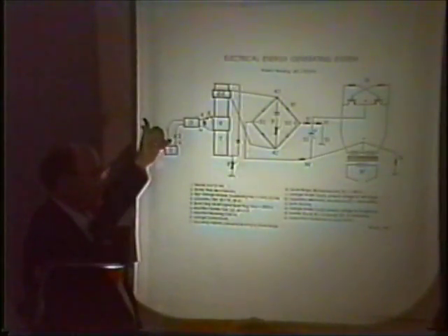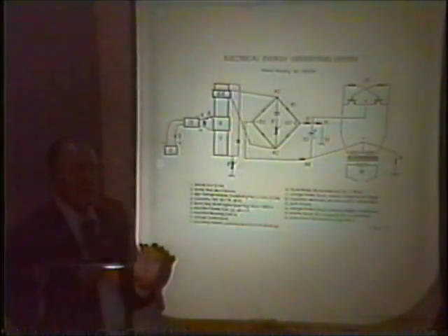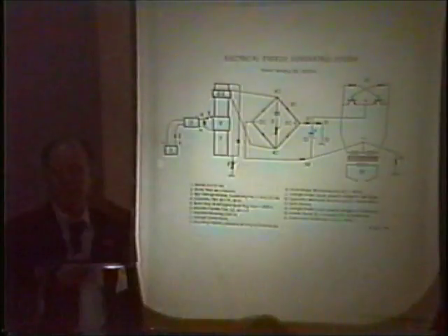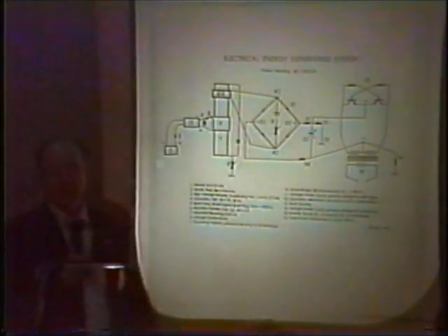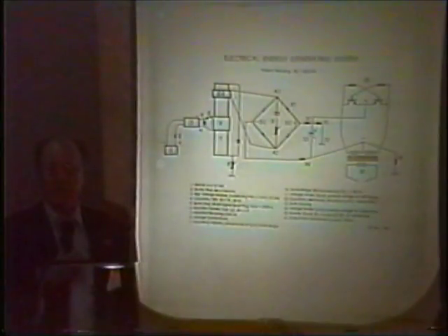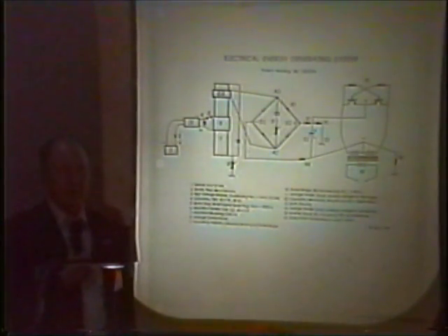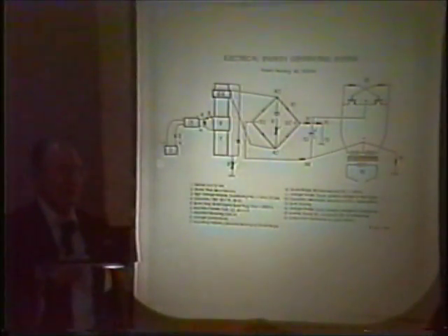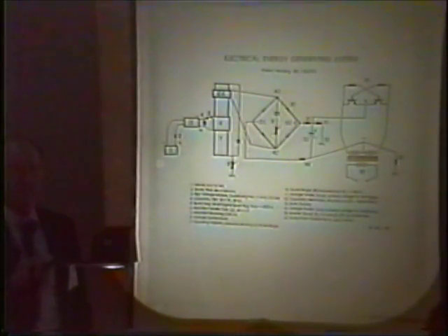Here's a diode that you put on your plus side so that you don't get a kickback. If you get a kickback, it damages your high voltage module. The high voltage module is a laser high voltage source like you'd have in your laser printer or whatever. They're available off the shelf, and if you buy them direct, they're a couple hundred or $300 maybe or something like that. If you're lucky enough to find one in an electronic surplus place, it might be as low as $50 or maybe even lower. So needless to say, I've gotten pretty good at finding the surplus ones.